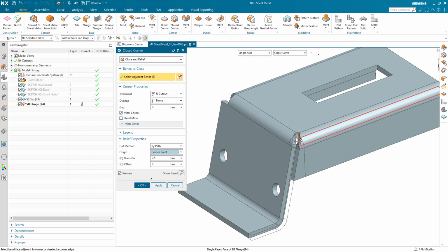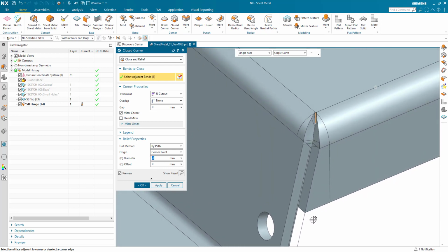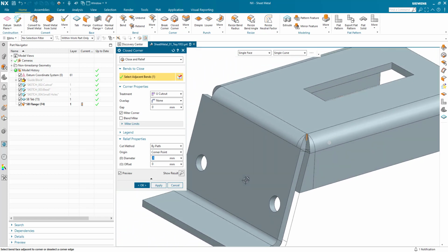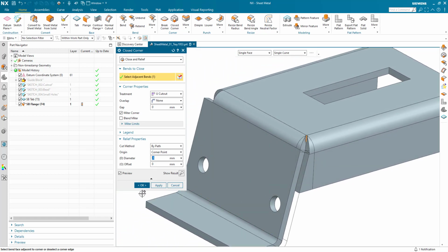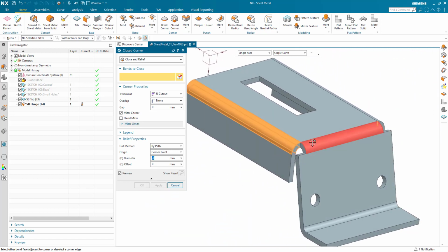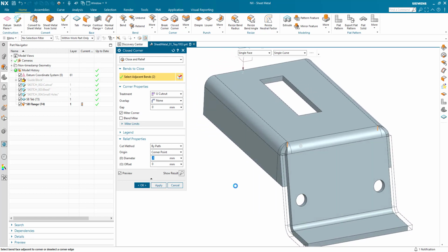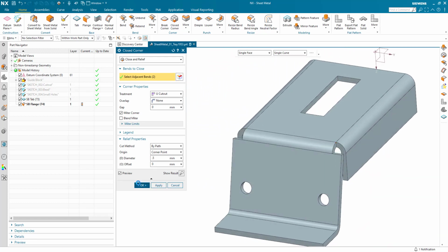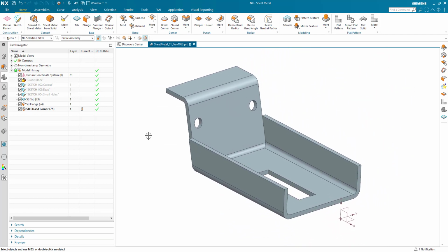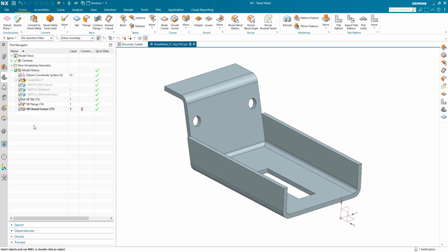And what we've done here is created a very clean cutaway and clearance, but I'm going to make that diameter of that clearance much smaller here, and it generates something that looks like a closed corner, but it is in fact a U shape here with a little bit of a gap there. I can generate a gap down, but I'm not going to do that for this. Now I can either OK this and repeat it on the other side, but what you can do with closed corner is just pick two more faces, and we can generate the corner on both sides simultaneously within a single feature. So I've effectively got a relatively complex design generated within 3 features.